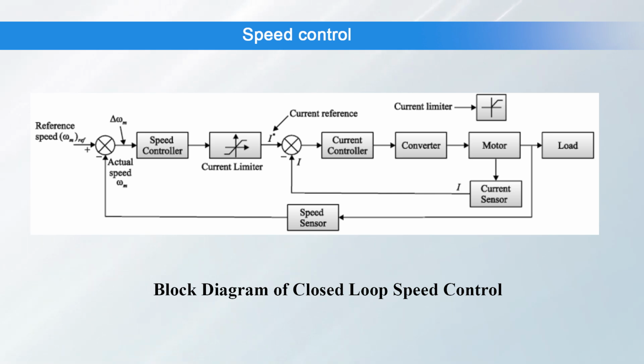The most common arrangement, which is used with only minor variations from small drives of say 0.5 kilowatt up to the largest industrial drives of several megawatts, is two loop control. This has an inner feedback loop to control the current and hence torque, and an outer loop to control speed. When position control is required, a further outer position loop is added. A two loop scheme for a thyristor DC drive is discussed first, but the essential features are the same in a chopper fed drive also. Later, the simple arrangements used in low cost small drives are discussed.